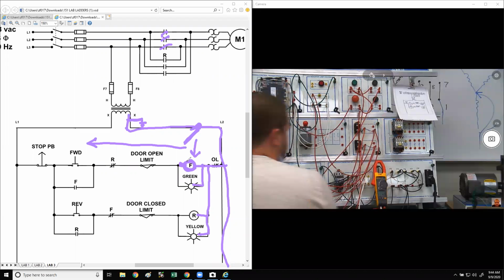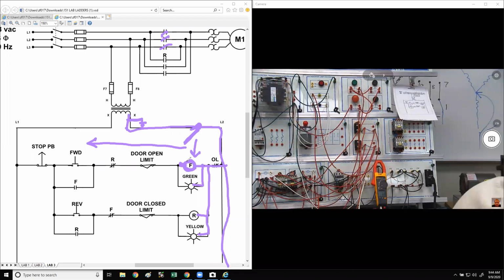What if I was getting voltage here? We're getting voltage there. Tell me. You have a bad coil. No, so I don't. I have no voltage here, and I have 120 here. You have a bad coil. No, because I'm not getting voltage to it. How's that coil going to do its job if I got 0 volts at it? So does that mean open? Yep, if I have 120 volts potential here and none here, that means that this wire is broken somewhere.